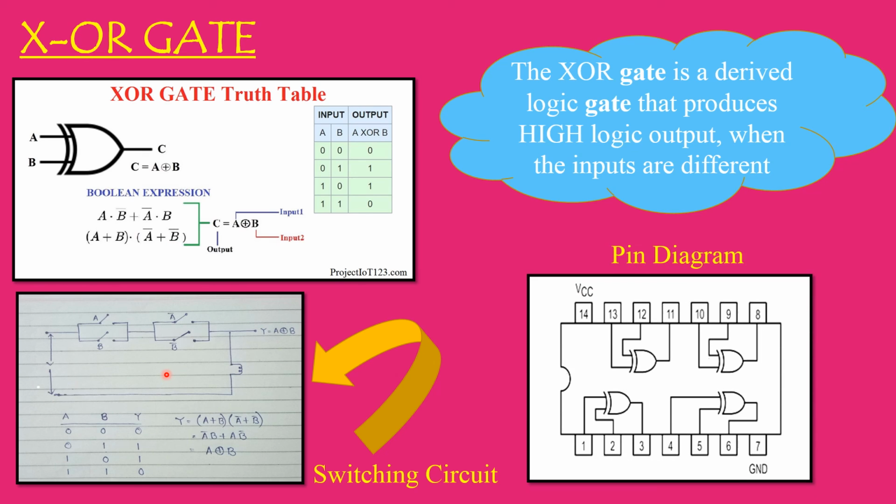So next, as usual, we'll see the pin diagram and the IC pin number. IC 7486 is always said to be your XOR IC. Even within this IC, you will have 4 XOR gates encapsulated. This arrangement is normal like your basic gates. You will have all your gates within your IC facing downwards, so you need not have any changes over here. All other things are the same like your basic gates configuration. But the IC number you have to remember. Got it?